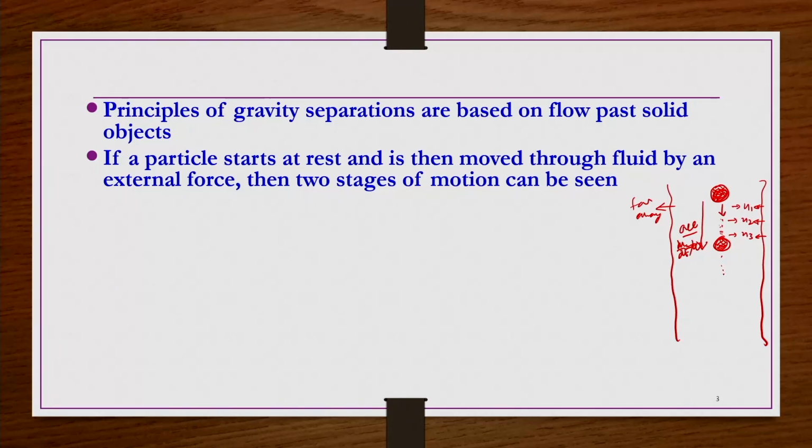But after a certain more distance, there will be a stage where the particle is settling with zero acceleration. Further with distance, its settling speed does not change with time. These conditions we call free settling conditions, where acceleration is 0.